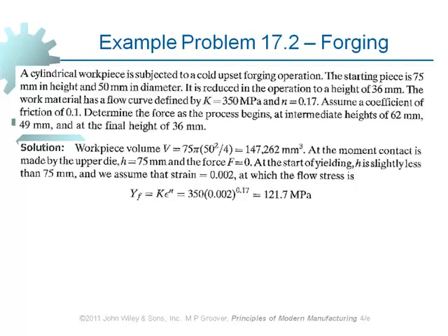What we do is draw a line which is offset from the linear region of the stress-strain curve. It's parallel to that one, offset by 0.2%, it's not 2%, okay? Whenever it intersects with the actual curve, the intersection gives us the magnitude of the yield stress. And that's what we need to use in this equation. How far do you offset it? 0.2%, a percent of the total strain converted into a fraction.